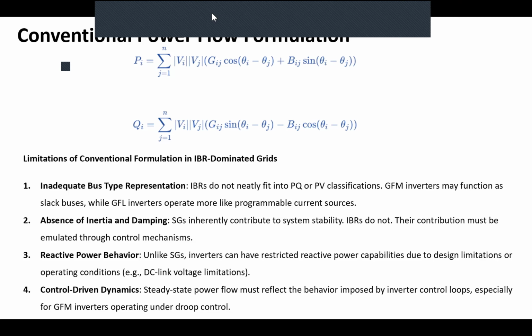So if the inverter wants to draw a massive or notable amount of reactive power while providing the demanded active power, then we're going to have a problem because it would exceed the level of capacity that our DC part has. So the inverter would face limitation on providing reactive power, meaning we are going to be a little bit shaky on stabilizing the level of the voltage. Are we good? So these are the parameters that would affect the power flow equations. Are we clear so far?